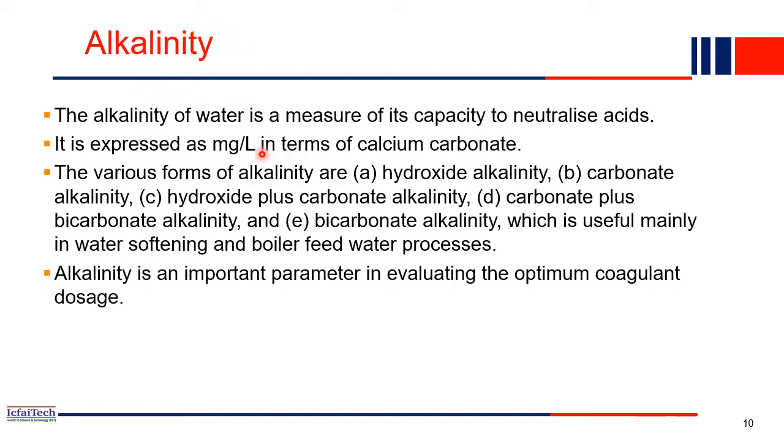Alkalinity may be present in the water in various forms, like hydroxide alkalinity, carbonate, or bicarbonate alkalinity. If these types of salts are present in the water, they will produce alkalinity. We express alkalinity in milligrams per liter.